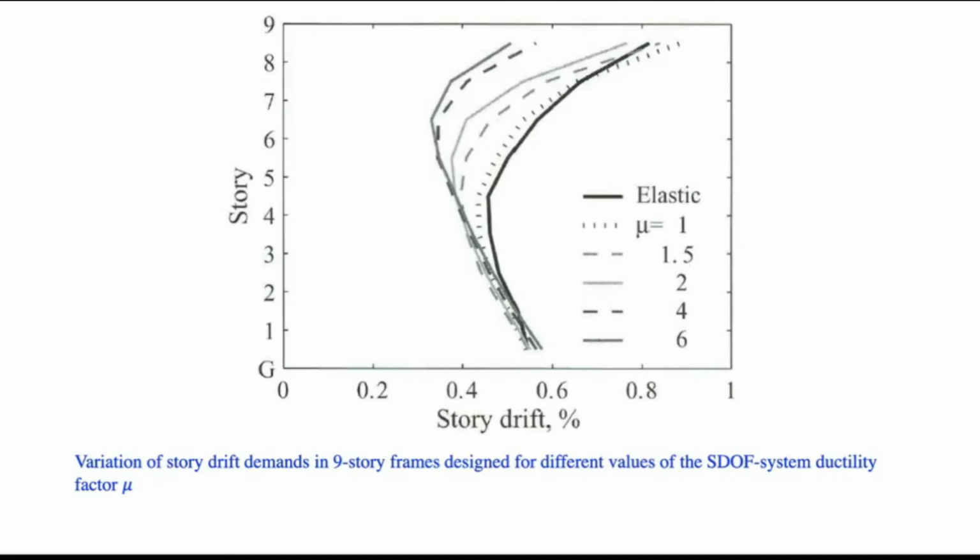Okay, so what we can see is that the story drift demand and its height-wise variation for an inelastic system differ from those of the elastic system and depend significantly on the ductility factor for which you design.